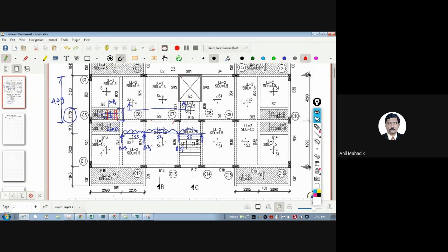It is a continuous slab. That means we will get moments like this. Yes or no? Yes. So there is a sagging moment, MS, and let's say there is a hogging moment, MH. That means I can say this is your fixed condition because there will be negative moment at this point, on this beam. There will be negative moment here. So if you draw the section like this, then you will find again negative moment here. So this is the concept of continuity. And is there any beam slab over here? No. So there is a discontinuity. So it will be 0 moment.